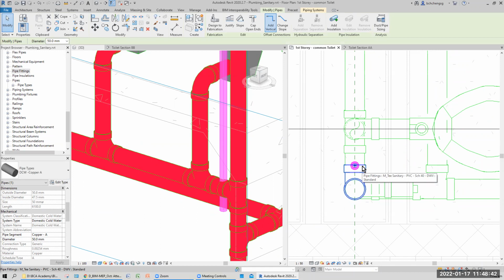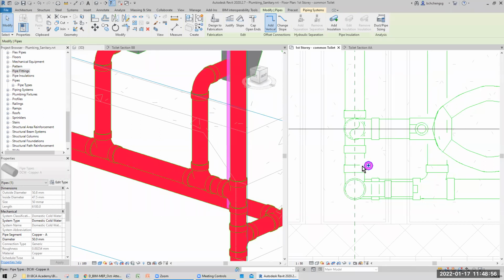When the water supply comes or the motor runs, you'll find that there's always vibration. So all these steel pipes must have a bracket to hold the pipe near the wall. So in other words, you could move them away and somewhere here. All right. So the bracket can be up a bit. I mean this pipe and somewhere here. Not so close. This bit is too close already.